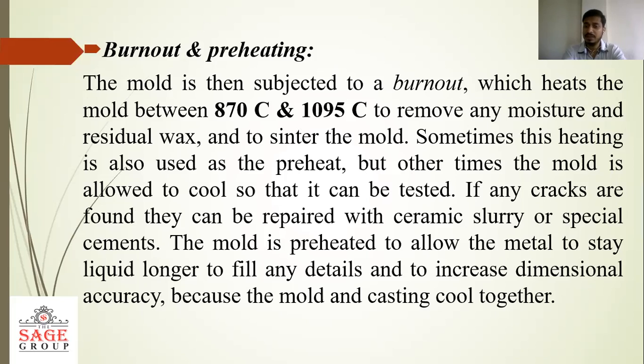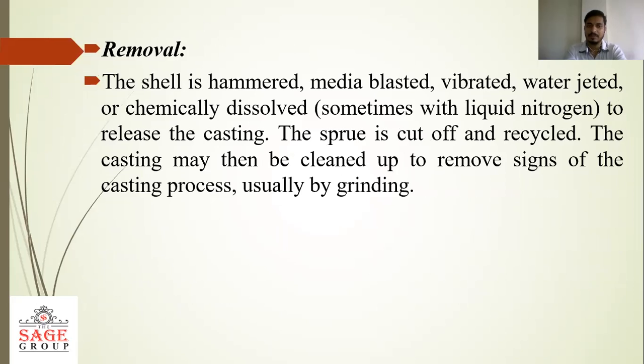The mold is preheated to allow the metal to stay liquid longer, to fill any detail, and to increase dimensional accuracy, because the mold and casting shrink together.